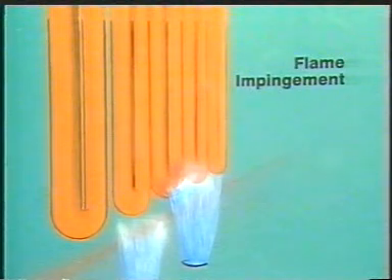Flame patterns should also be inspected on a regular basis. The flame should be bright and clean with no trace of smoke. A properly burning gas flame is blue and compact, while an oil flame tends to be bright yellow. Flame should not touch the tubes. This is called flame impingement. Flame impingement can quickly damage a tube and cause it to rupture.